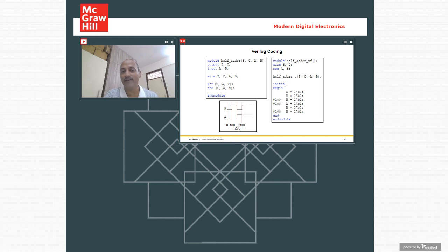On a synthesis tool, or when we are working with a silicon chip, it is not possible for us to hold the signal for 100 nanoseconds, right? The only way to do that is to pass it through a flip-flop or registers, or pass it through a chain of inverters, or fabricate a delay line and then delay the signal.